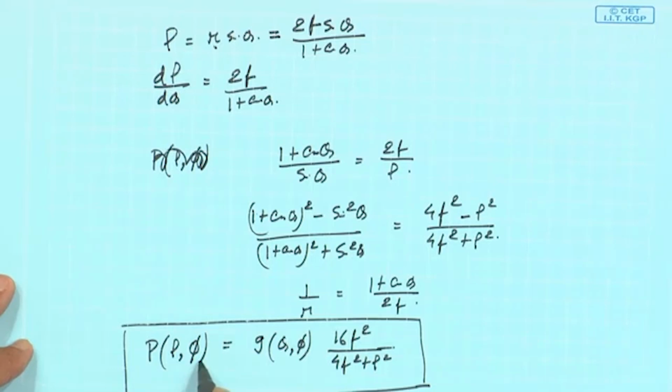The same thing in a distributed fashion: if you uniformly illuminate with same phase distribution, same amplitude, then you get a very peaky pattern along the broadside. So that is always desirable, because that gives you maximum directivity. So always that is a dream. So if I want to make P rho phi uniform, then what is my requirement on G theta phi?